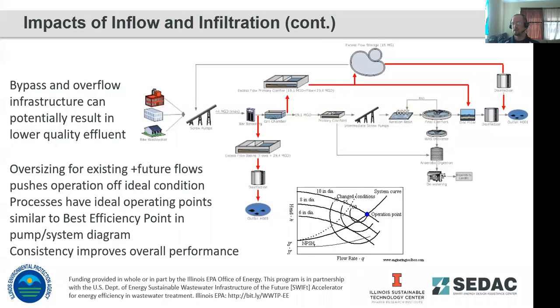From there, once flows are reduced and the disinfection system can handle those flow rates, then they just pump that settled and cleared water to disinfection and out to the outfall. For further increased flows, they've got a secondary set of excess clarifiers. And again, those treat those flows, reduce solids as much as possible, send it through disinfection and the outfall.